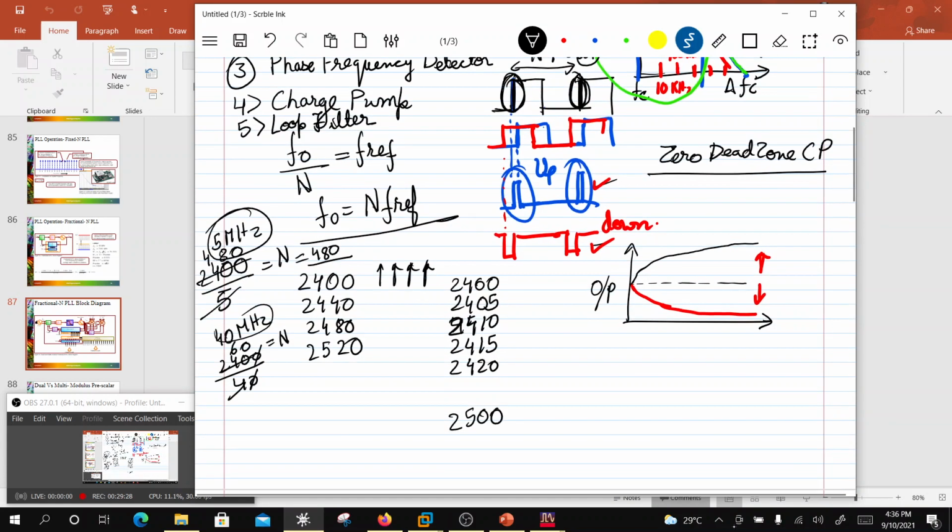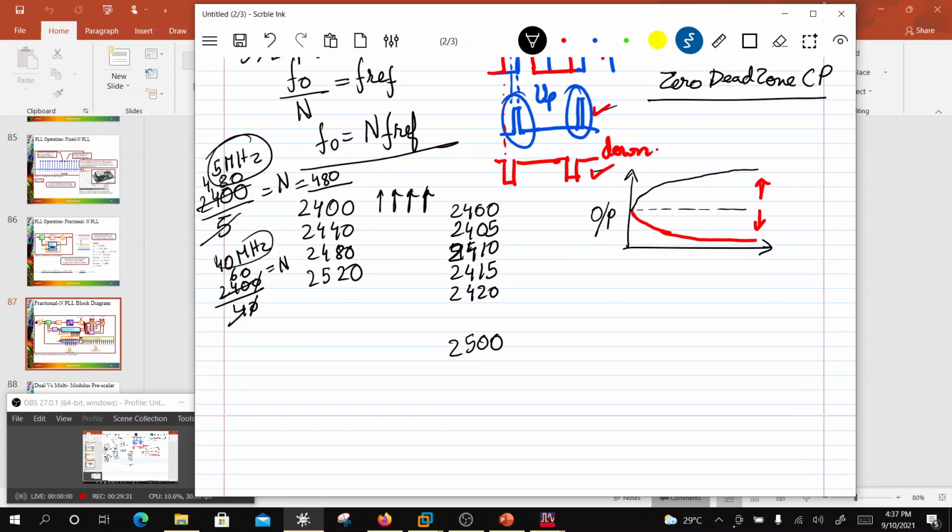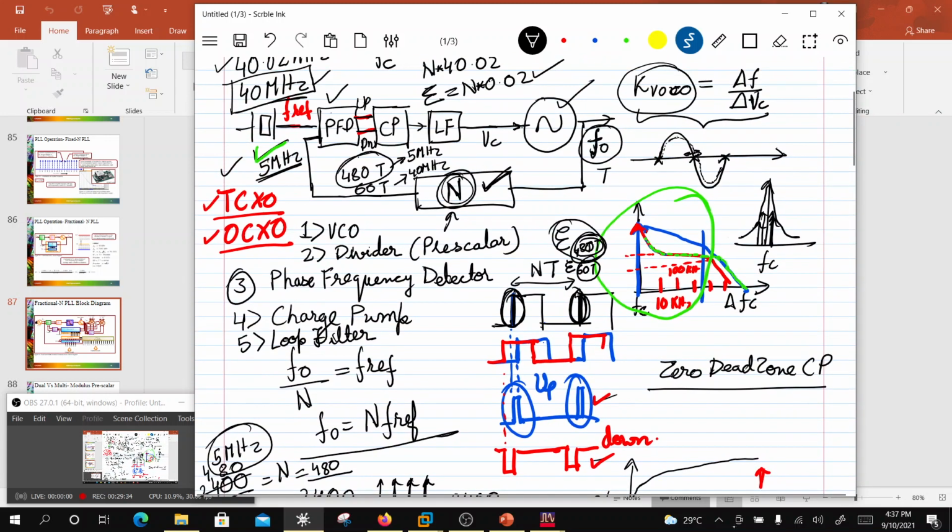This can also be shown in terms of Z transform, and in that case there is a relationship between the sampling frequency and the output frequency. If the sampling frequency and output frequency ratio goes beyond a certain permissible limit, then the response goes out of the unit Z equal to 1 circle, or stability circle, and then it is unstable. So digital systems are going to be unstable if the sampling rate is not correct for a given output frequency. I hope you understand.